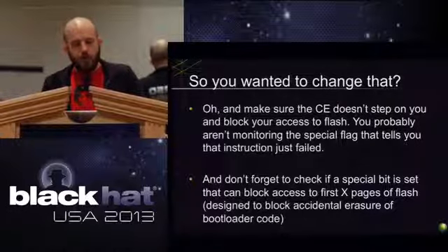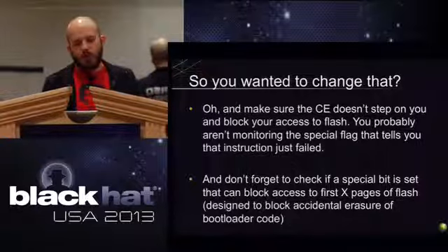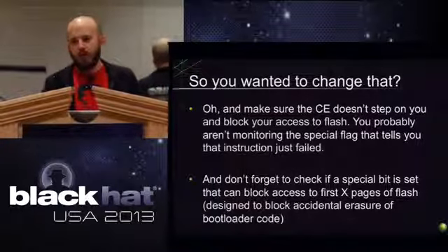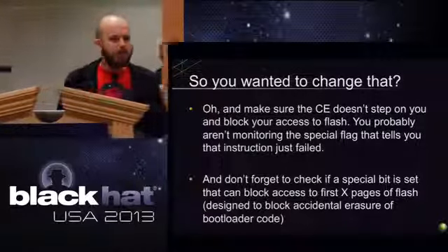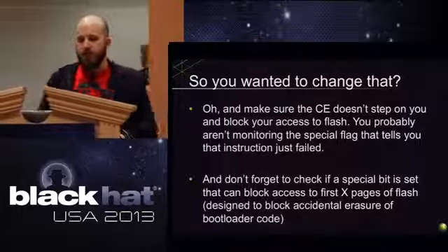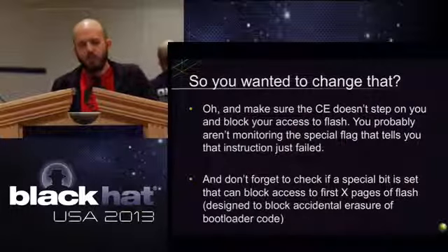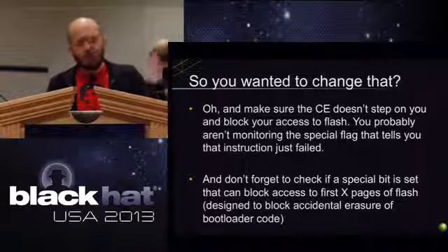It has a way for you to set certain bits that say turn off the first X pages of flash from being able to be mass overwritten. So that would typically be where you would store boot code, for example. Something like a failsafe, or the code that loads everything else. And so you put that there, and then you never want it to be overwritten. But it's just a bit, so there's not a security feature of that. You can just go in and change it if you need to.